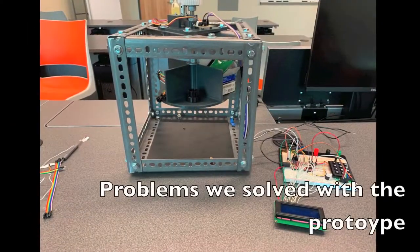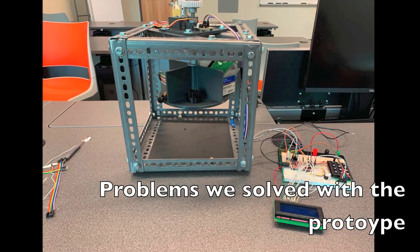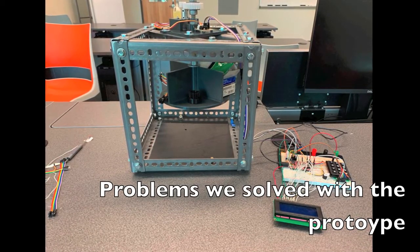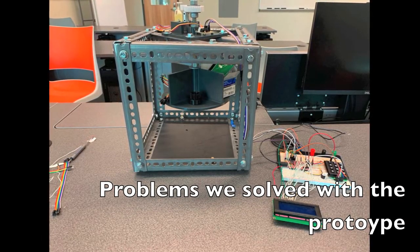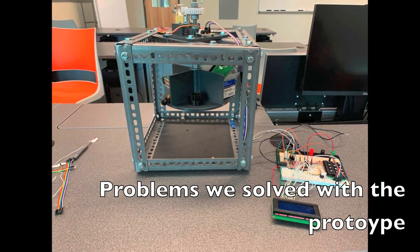Throughout the semester, we were able to solve a few of the open-ended questions we had during the design phase. We proved that pre-drilled steel framing could be used to create a strong frame for our prototype, a feature that could be simply scaled for our larger future machine. The electrical team was able to produce a functional program to store, remember, and deliver parts. It can withstand power outages and mechanical resets without losing data.